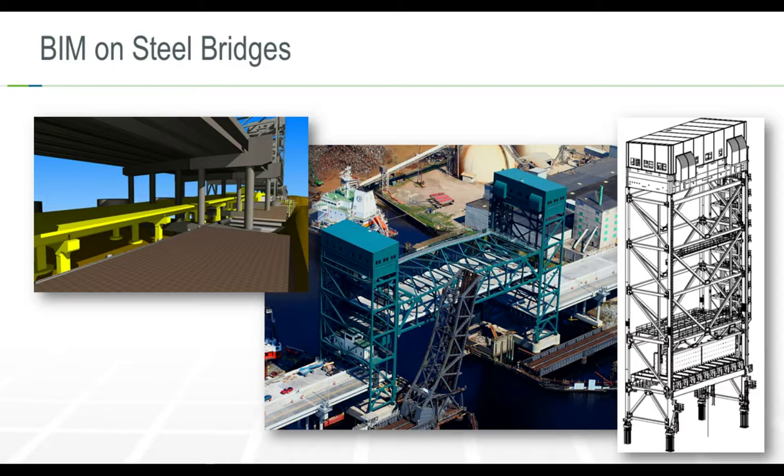all of the bridge was actually detailed in Tekla, which is a steel building information modeling software. And this was really key for us because we were able to identify bolts, create assemblies, verify weights and centers of gravity of a lot of the pieces, and then push that downstream into a database that we used for erection and actually float-in planning.